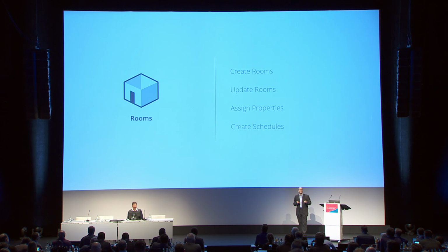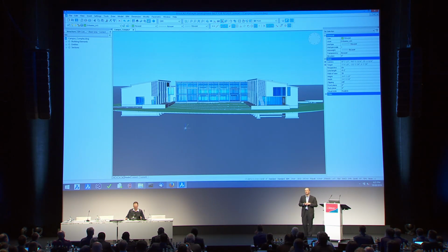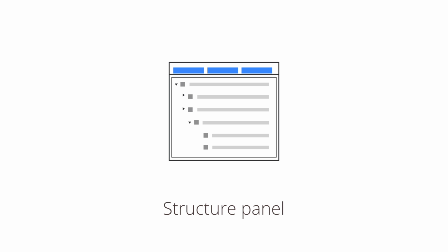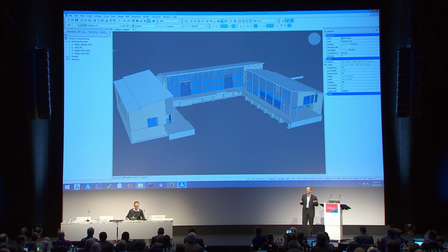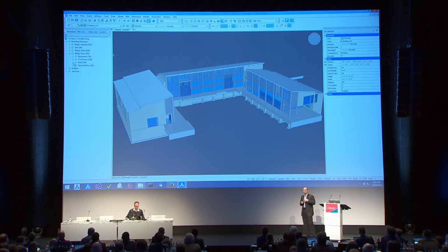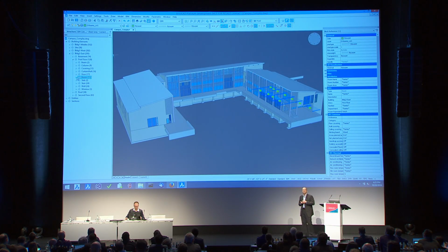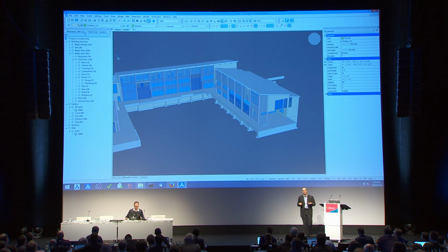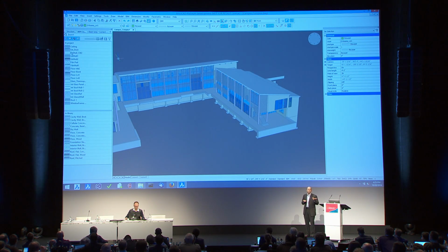You can assign properties to those rooms, and you can also do data extraction on those rooms, and we call it Campus Complex. It's 3 different buildings that are incorporated in the BIM. It's multi-levels. As I mentioned before, everything that's in the model is represented in this browser. And then we can expand this tree further. We can select them, and we could expand that and see that there's 11 rooms in there. Now, if you have the compositions set up, then you can expose the compositions browser. You can select the composition that you want. You can drag and drop it onto that component.